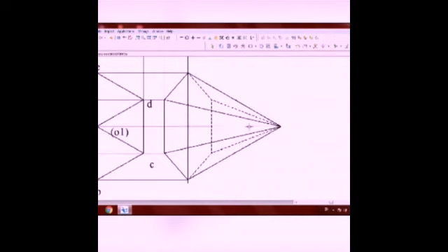That is the axis line. To make it visible as axis, remove or trim the construction line. Draw a fresh line from the base point, that's O1, to O, the apex. Then select that particular line and make it an axis line, not a dotted line. Axis line. That is the axis line now.